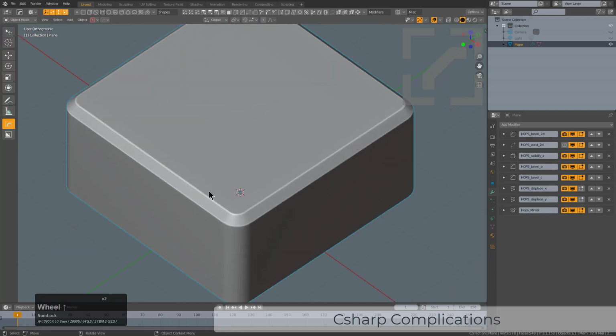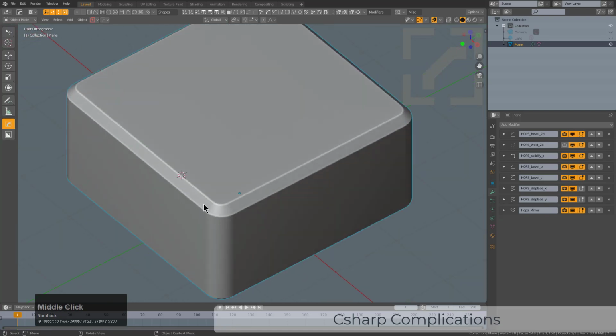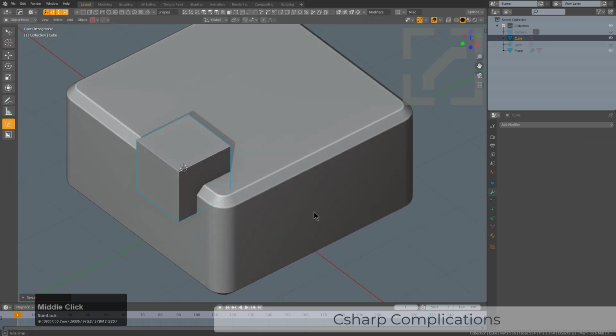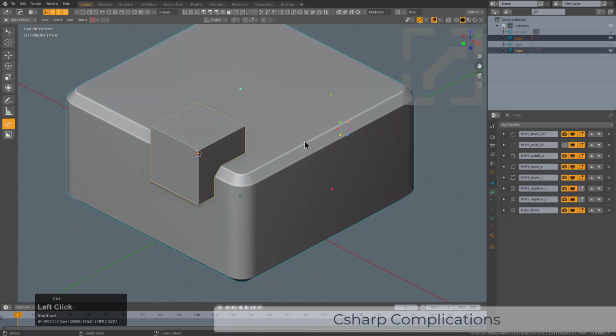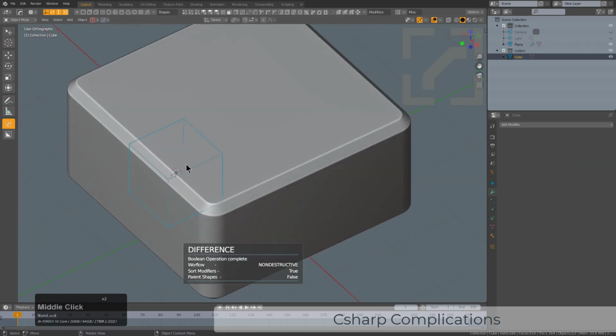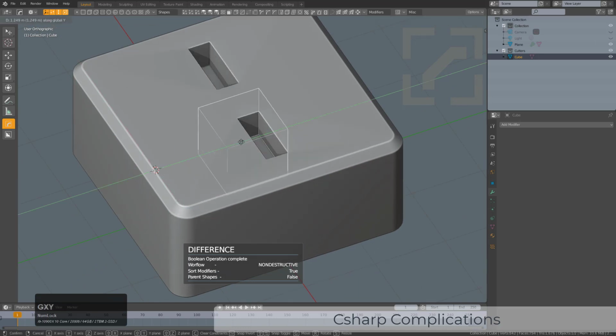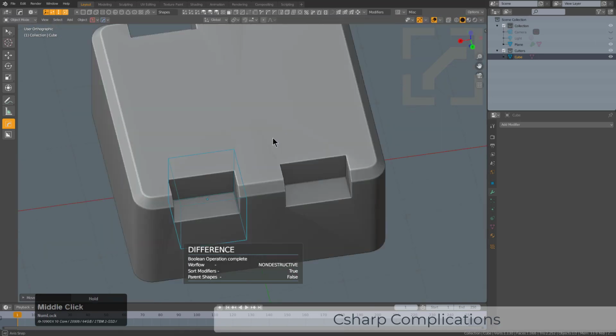But continuing on, I'm going to shift right click to place my cursor. And since we're in hops tool, I don't have to actually use any hotkeys. So we'll just select both of these and I'll hold control to bring up the hops ring, and we'll choose cut. And we see that it didn't actually take place, and this is because I cut on the side that we added via the fake mirror.